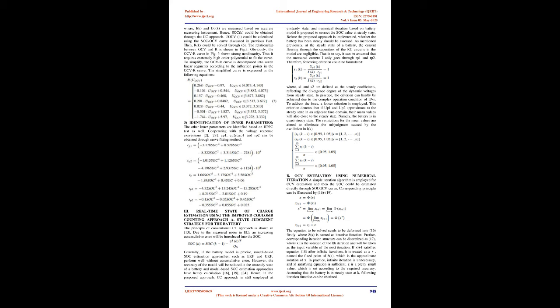2. Identification of R-OCV curve. The R-OCV curve will be utilized in the numerical iteration approach, which will be discussed in Section 3. Hence, the identification accuracy of R is critical. Generally, the lumped resistance R defined in (5) can be calculated through the identification of RO, RP1 and RP2, respectively. However, the curve fitting errors of RO, RP1 and RP2 will decrease the accuracy of R.